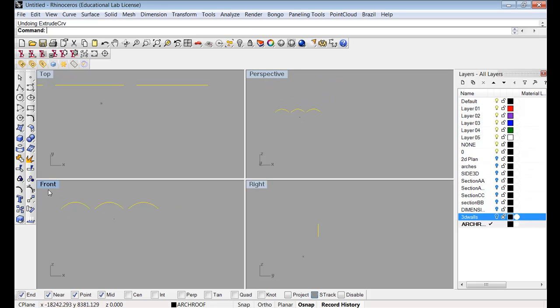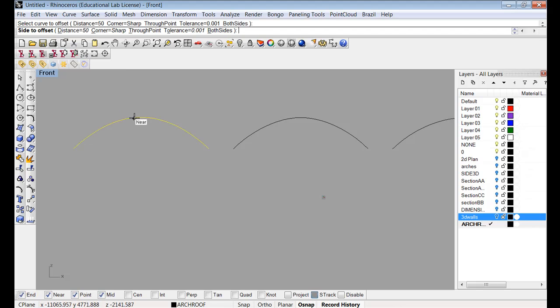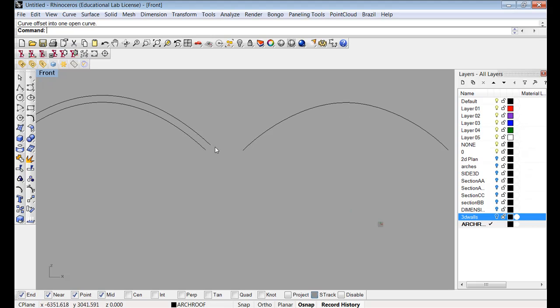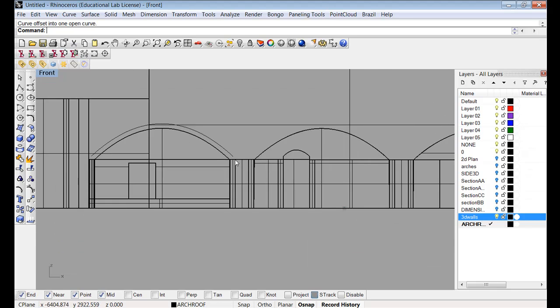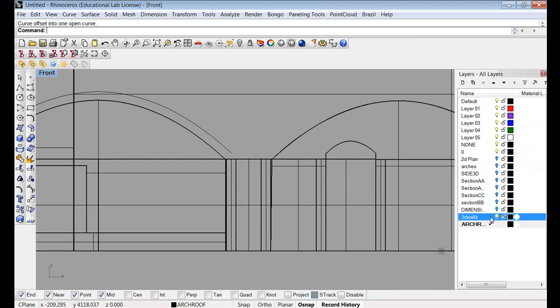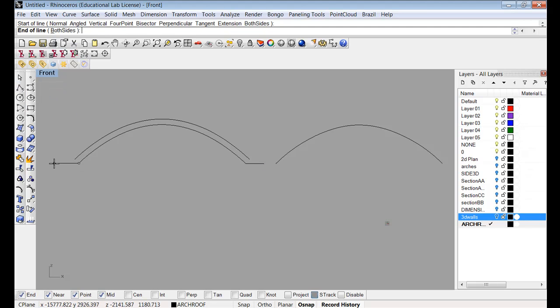if I go back into here and I go to my front plane, offset distance 270. Right, so I've offset that. There we go. So if I turn my 3D wall on, I can see it's nearly there. Right. What I can do is I can basically create a line. I think those walls should be about 270. So create a line from there to there.